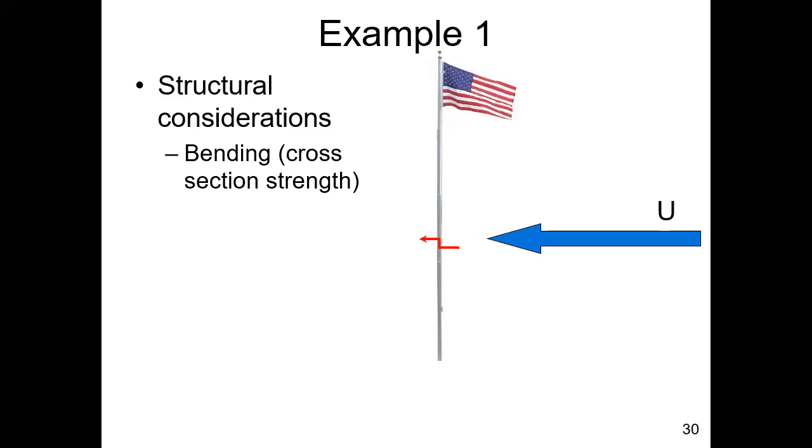And so at any location in the cross-section, the flagpole is bending like this. And that's putting this side in compression and this side in tension. Both of those are creating stresses. Some materials, aluminum, steel, might be better able to resist these than something that's not very flexible, concrete. Concrete's really good at compression, but it's horrible in tension. It doesn't really support tension.